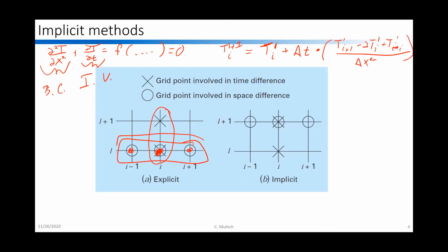So we're using these 3 points down here and then this point up here. And so when we do this out, we end up having to take relatively small time steps in the time direction relative to the points in the space direction, because we're using less information, and so that we don't have this oscillatory behavior.